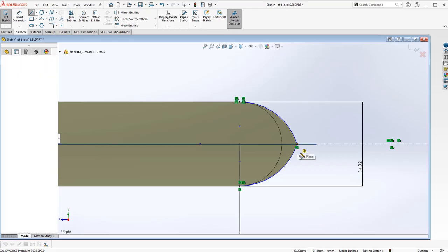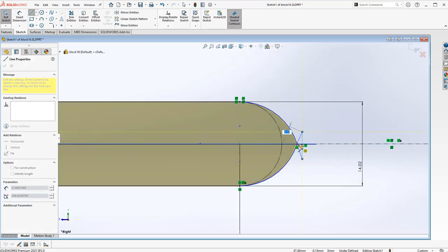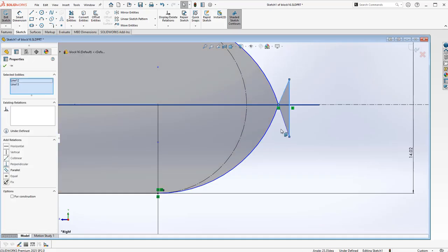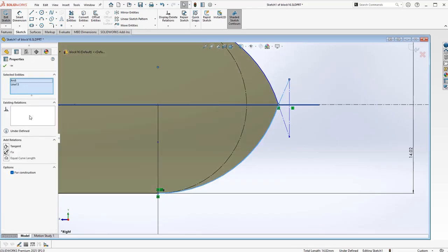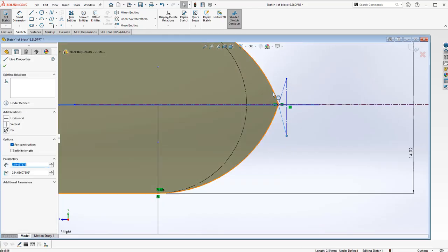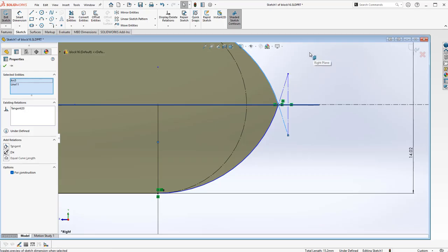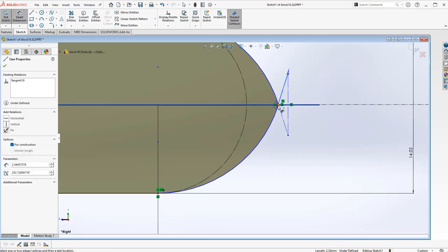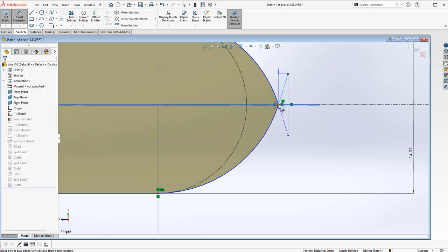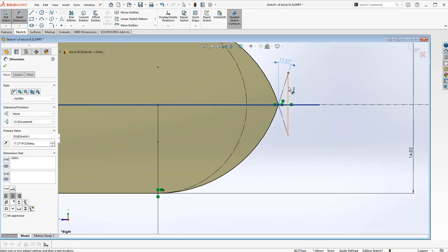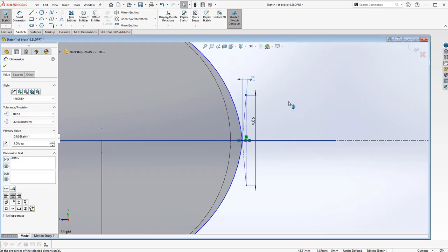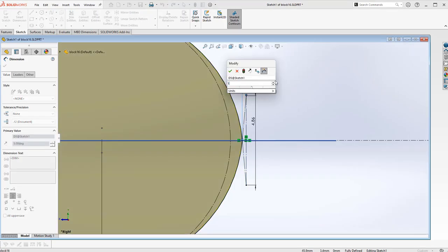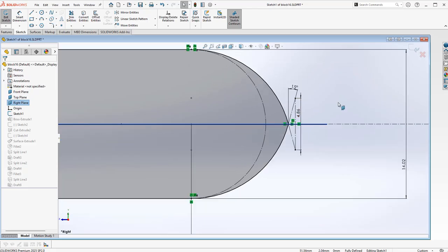Let's build this geometry the way we did before. While that's highlighted, I would reach for construction geometry, establish my tangencies, establish the angle, theta. Great. Exercise it to see it flex through the rotation. I need 15. I need 10, but I'm going to set it to 15 for now. This number is irrelevant. Check out of it.